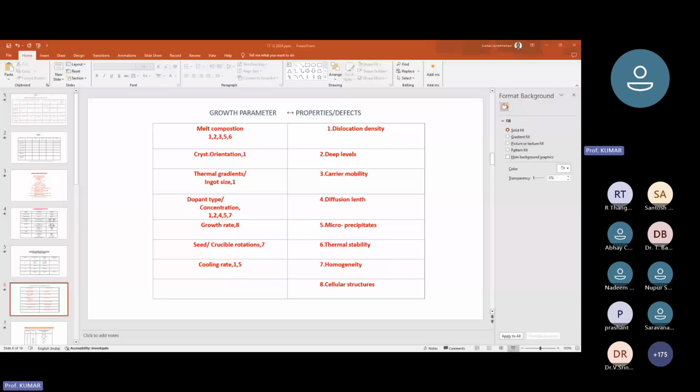So there are various materials which are being used as dopants, which means you can selectively take a particular element depending on the free carriers or the excess electron it will possess. For example, sulfur is a sixth group element. So in three-five compound semiconductors, it will replace the arsenic, which is the fifth group element.